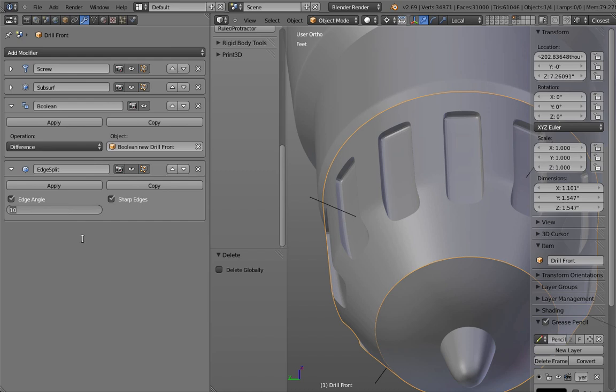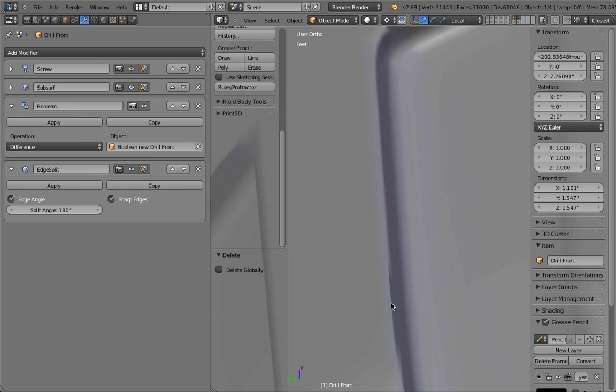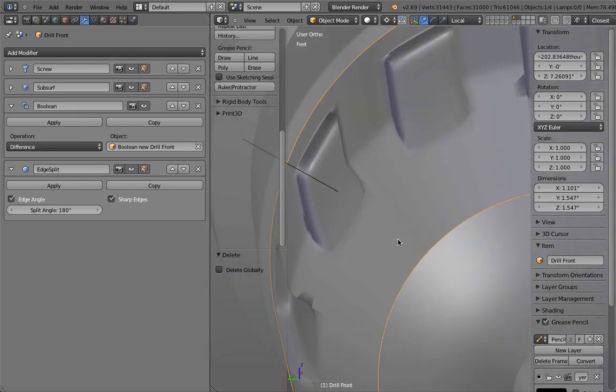If it's, for example, 0 to 20 degrees, 0 to 90 degrees, it starts to, how could I say that? The higher the degree, the more the software tries to soften everything. So for example, you see those edges look soft, but they are rather sharp. So that's the reason why you get these artifacts.